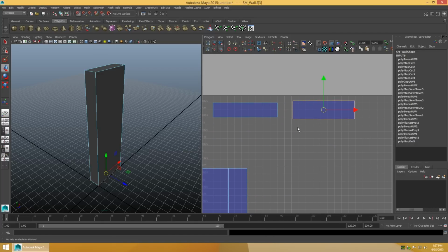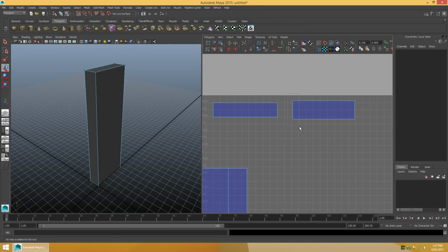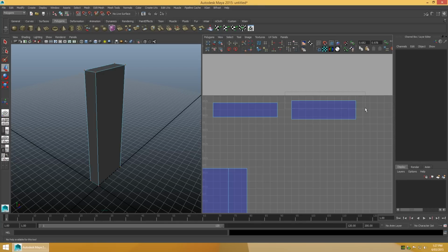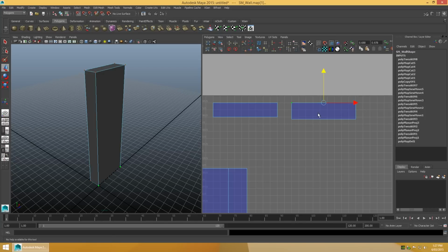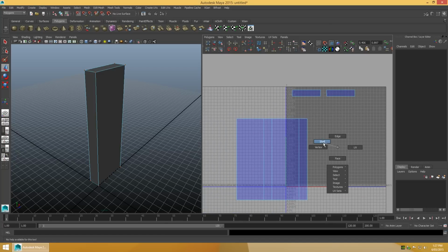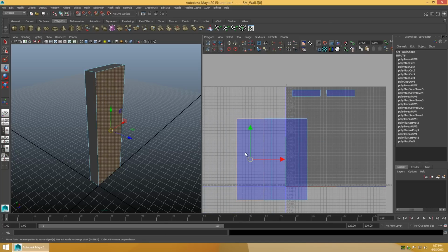So how much space should be between each UV shell? At minimum, there should be one grid space, which is equivalent to 1 pixel with a Lightmap resolution of 32, between each UV shell. Ultimately, if the mesh is simplistic enough that this number can be increased, then it should be, as it minimizes the likelihood of issues occurring. In this example, there are 2 grid spaces between each UV shell.